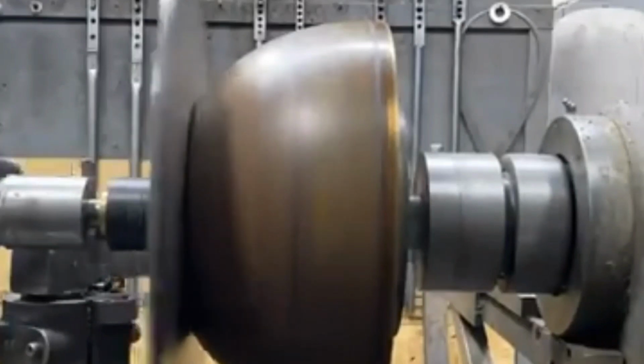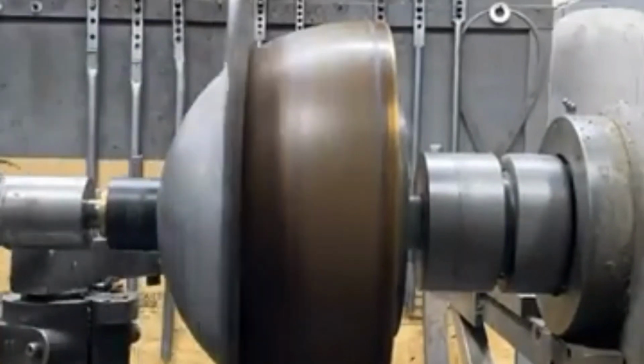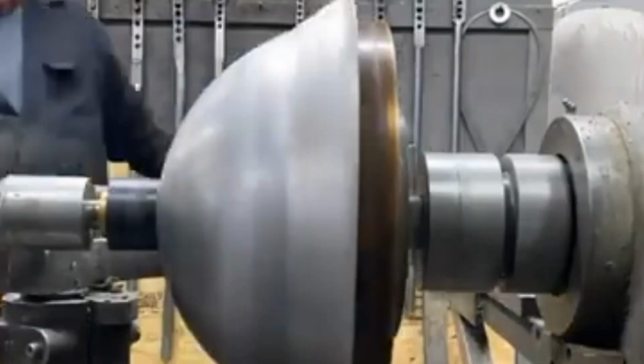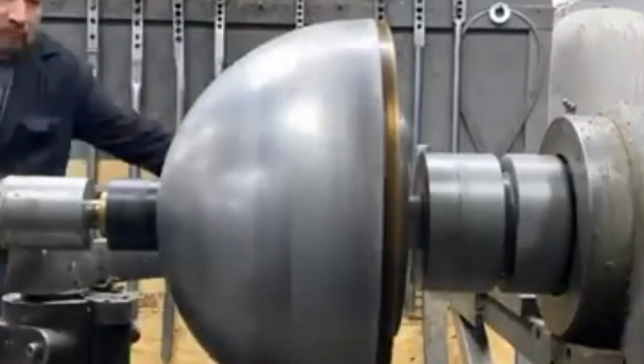Unlike dishing, other sphere fabrication methods do involve thinning or stretching of the metal sheet. And since this deformation varies depending on lots of different factors, it cannot be considered within the calculation method. So, in addition to dishing, there is spinning, stamping, and even hydroforming. Spinning is the process where a flat sheet of metal is gradually formed into a shape by pressing it against a spinning, in this case hemispherical mandrel. This method is commonly used for relatively thin walled spheres.